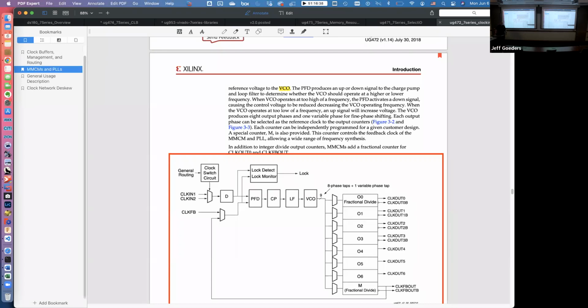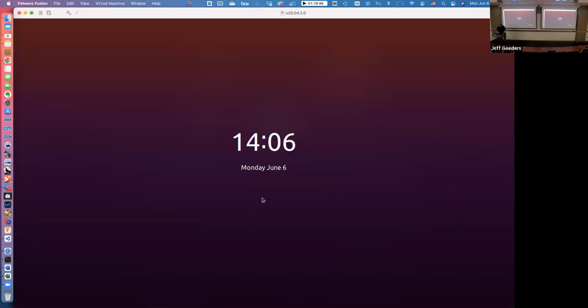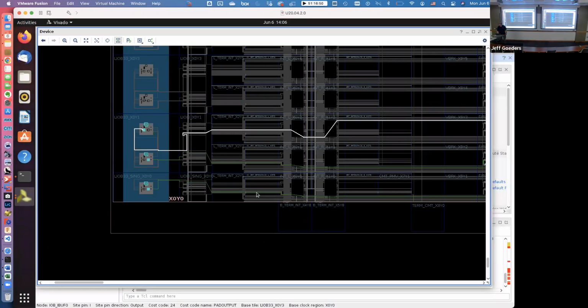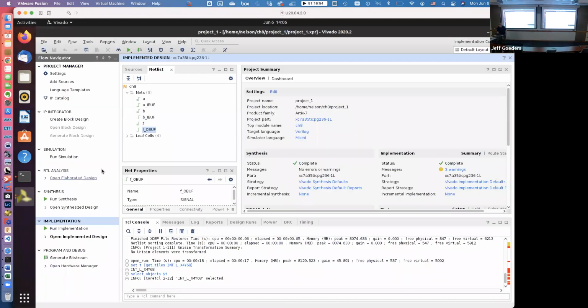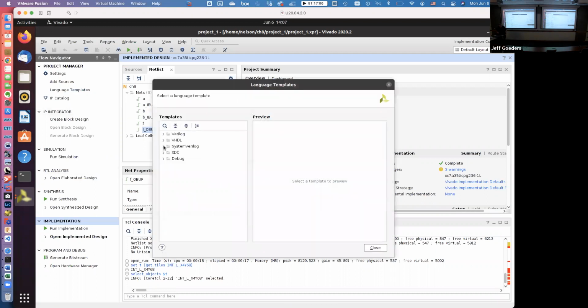It does the primitives, the XDC file. It also does interfaces, if you want to implement an interface in the block diagram and stuff like that. Here, let's do it. How do you show us where? This is something I have never used. It's good we're done, because I'd be out of time. Language templates are up there under Project Manager. There we go, Language Templates. Okay, just hit the magnifying glass and you can search the primitive and it gives you examples.